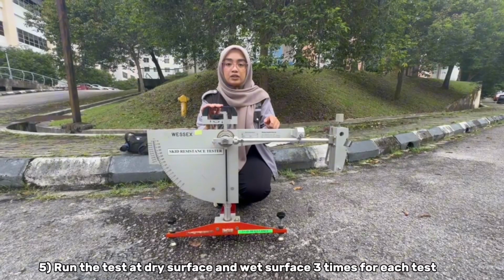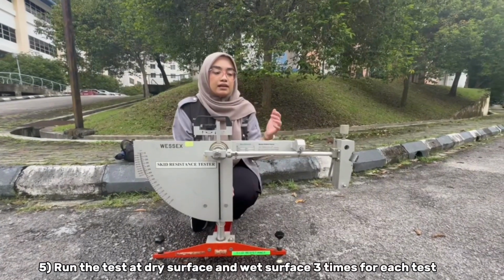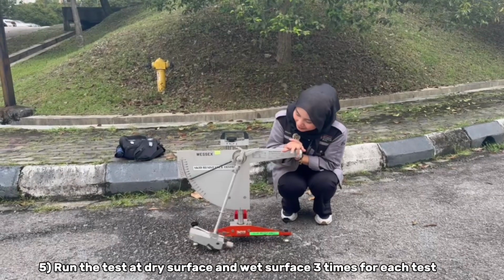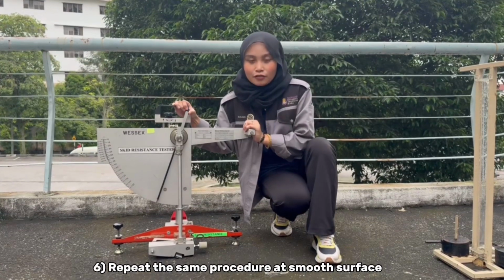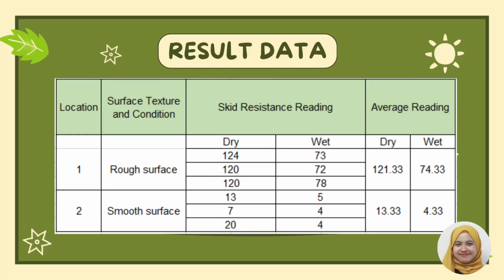So now we will do the skid resistance test for wet surface. We will take again 3 readings for wet surface. Next, we will conduct the same experiment for the smooth surface. Now for the skid resistance test, we do it for the rough and smooth surface, but in different conditions for each surface, which is dry and wet. For each surface with different condition, we take 3 readings and do the average to get the British pendulum